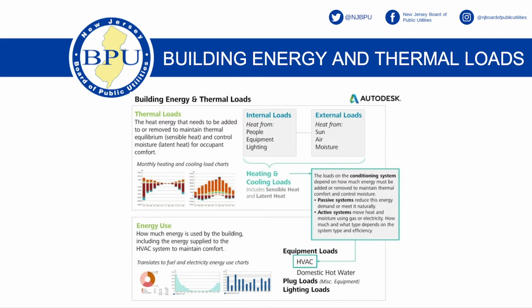And internal loads, all this lighting we have puts off, besides light, what else? A lot of heat. And that heat doesn't go anywhere but in here, right? So if you're putting it in here and it's a hot day, now you have to remove it. So it makes sense to have lighting in the whole building approach that will not only provide you lighting for less, but also reduce the cooling load.